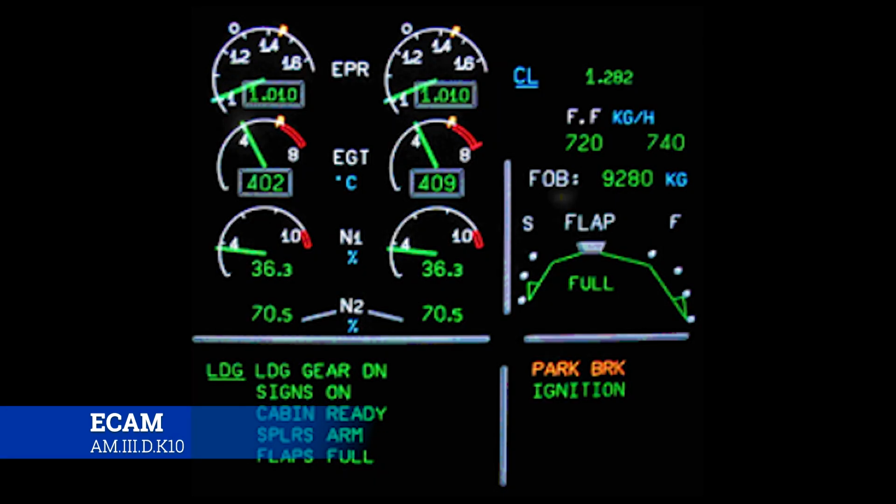Now let's talk about the ECAM system, electronic centralized aircraft monitoring systems. Okay, so this is ECAM. It is the electronic centralized aircraft monitoring. Now, ECAM is a little bit different than EICAS. They both focus on the same systems. They provide the same data and everything else, but it emphasizes automation and procedural guidance. Like, so do this, don't do that. Whereas EICAS prioritizes alerting the crew, just letting you know what's going on, so that way you can make the decision.